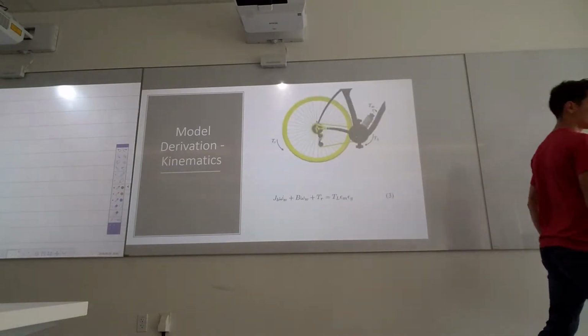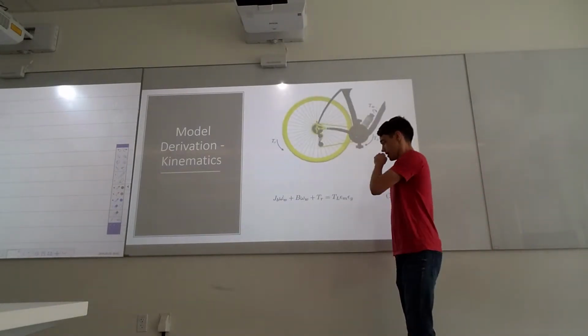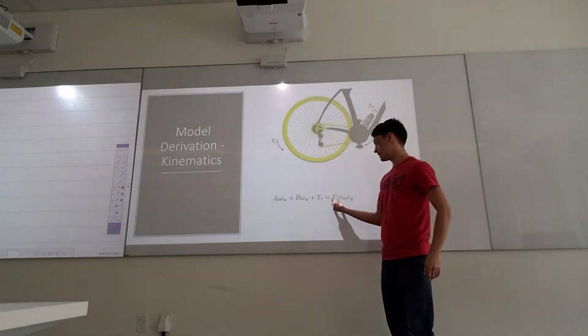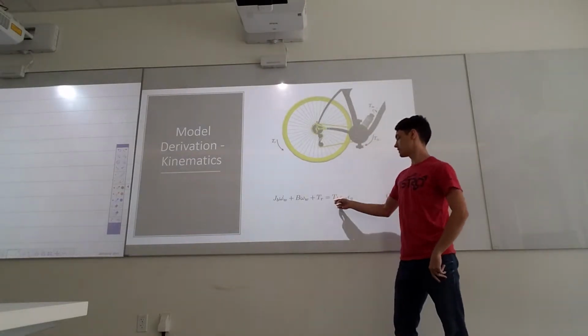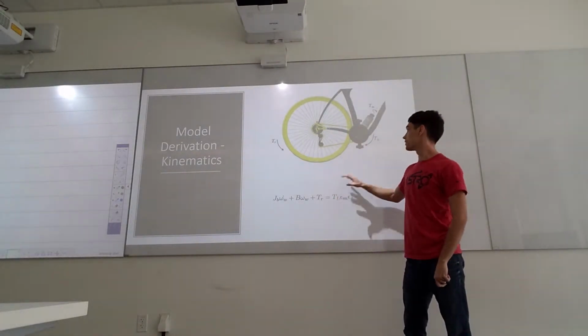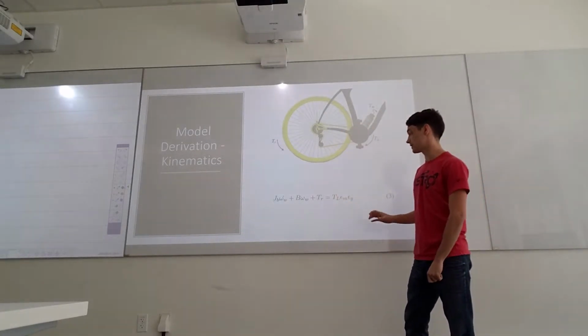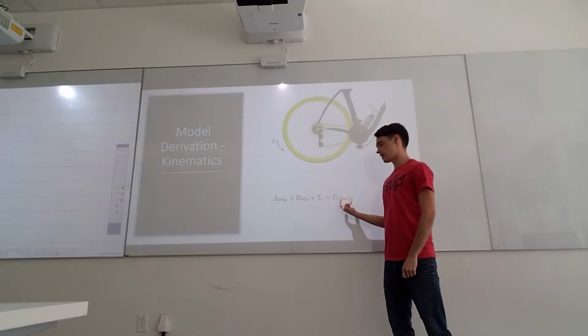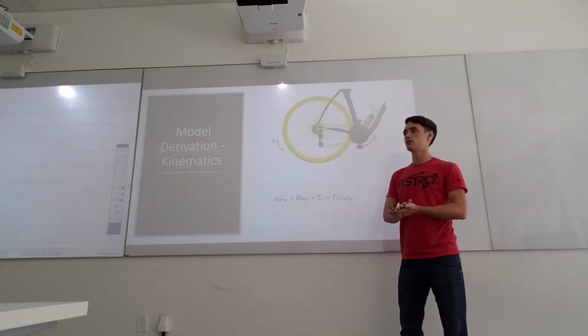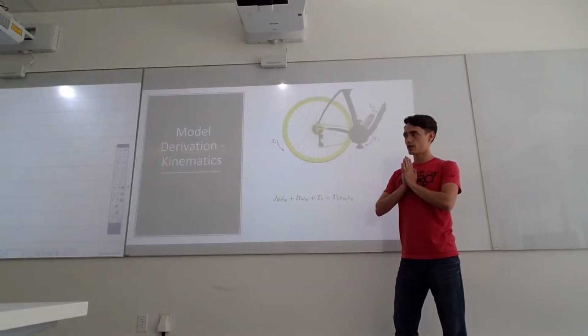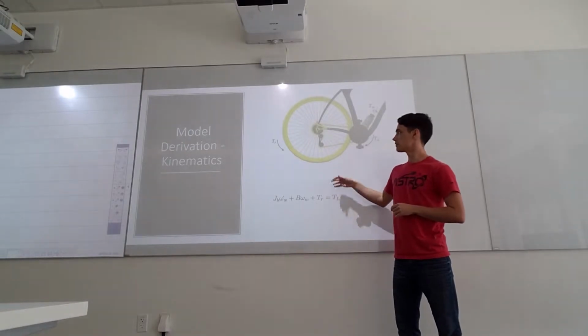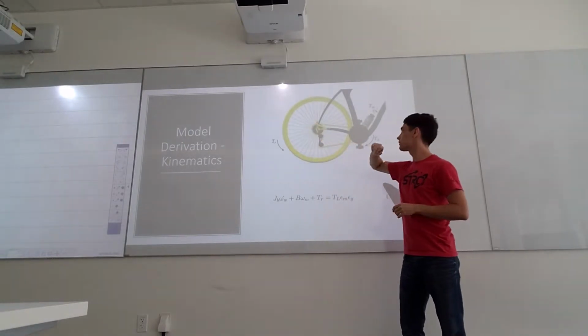Now for the bike kinematics, we saw that TL was actually what was being input, so this is actually the force on the load, which in our case is the bike, from the motor's perspective, I should say, that's the force on the load. So epsilon M and G actually serve to convert this TL all the way to the wheel through gear reductions.